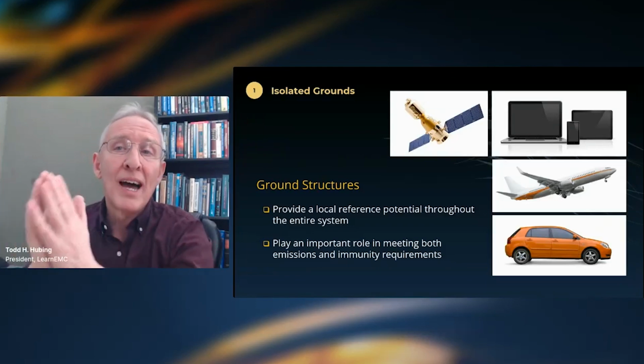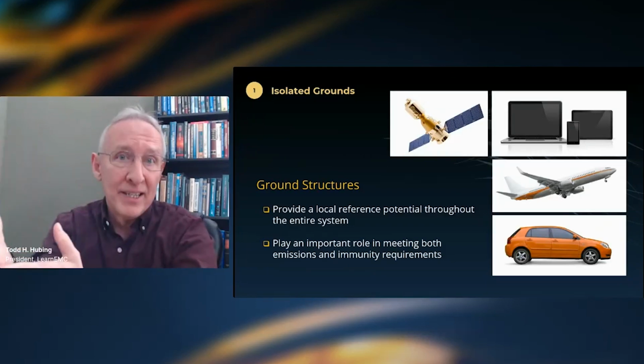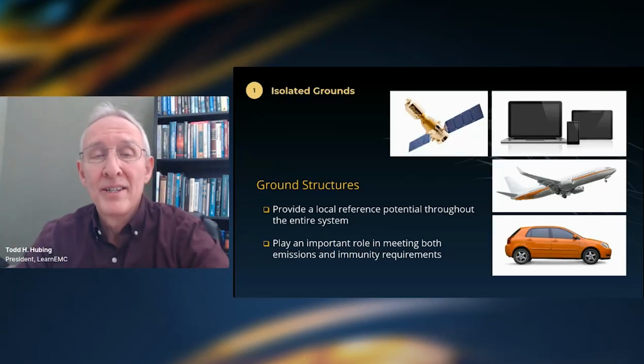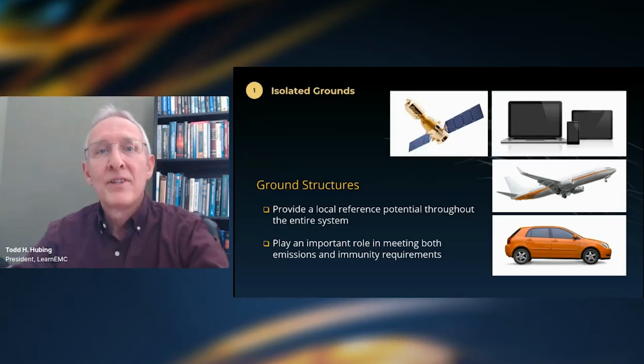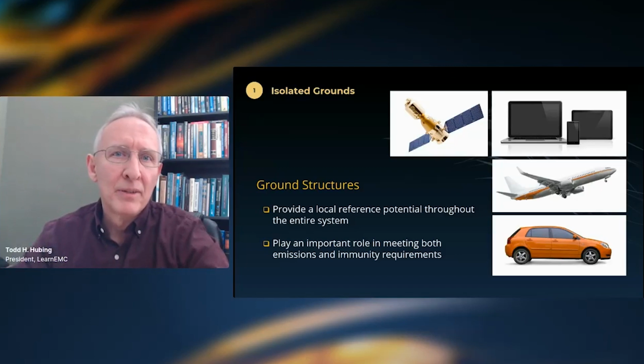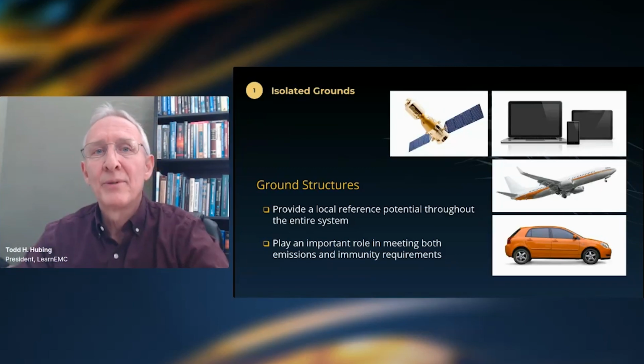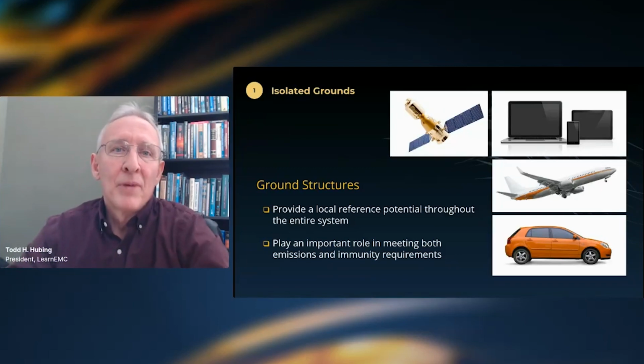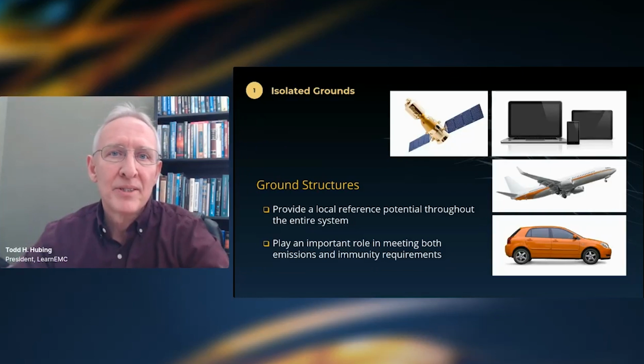Basically, if I don't drive any other pieces of metal that are of resonant size relative to the ground structure with about a millivolt or more of voltage at any given frequency, I'm going to be compliant with the radiated emissions tests. I want to bond everything to that ground structure that I can. And if I can't, then I need to deal with that.